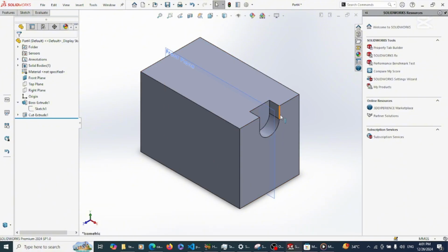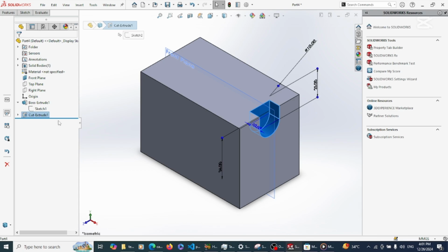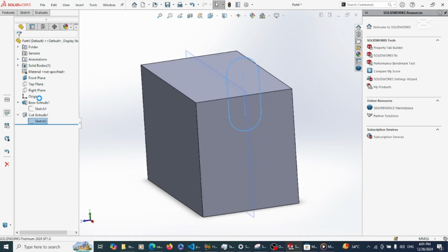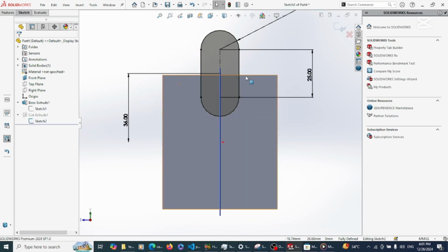We notice that this one has moved. Why did this one move? It was because of the centralizing we did here before in this sketch. Let me go here. This sketch here, remember we used dimensions to centralize it. Before I came back later to use relations, vertical and horizontal relations, to centralize it. So for this one, it's still dimensions we use to centralize. So it's going to follow those dimensions, if you get the logic.